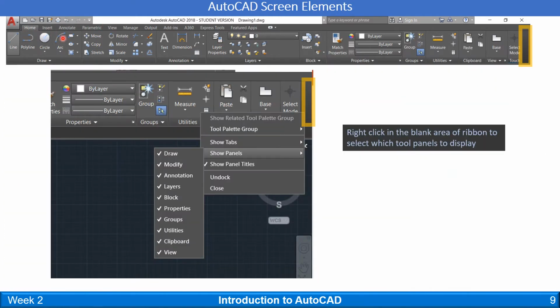Okay, let's say you want to customize what tools are in your ribbon and what order they're in. What you do, again, you're going to find a little blank spot in the ribbon where there's no buttons, so right here on the very edge. And if you right click over here at the very edge, it's going to bring up everything that is shown in that window. So if I come over here to show panel tiles, and right now I have everything selected. So when I select draw, that means my drawing tools up here. When I have modify selected, that means modify.